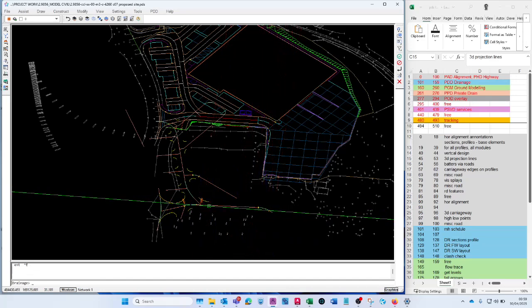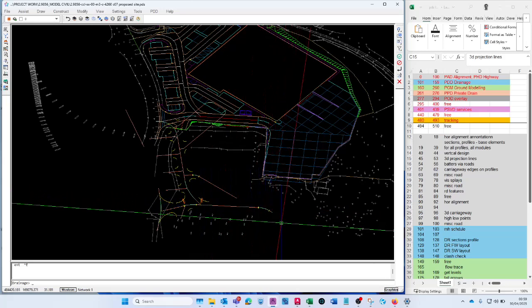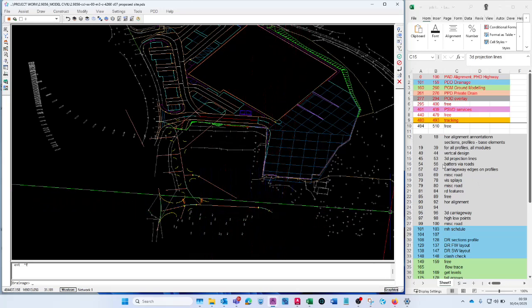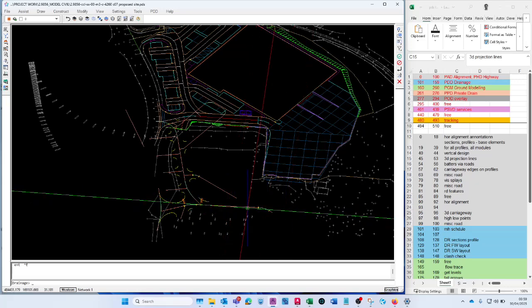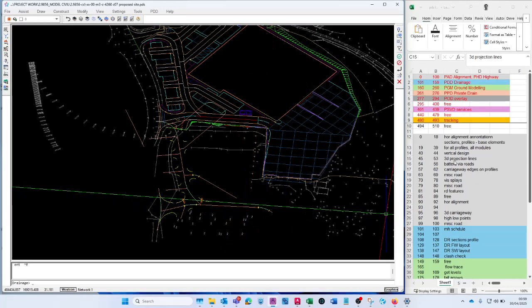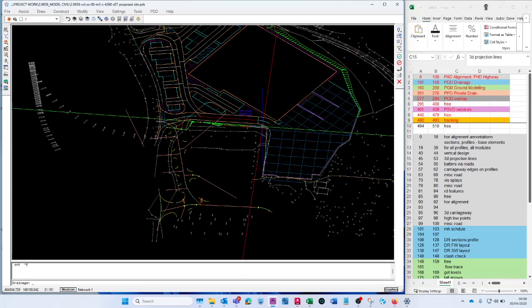So the truck is going to go straight along this road. It's going to turn and follow this little stub road. And so this is the 2D information that you set for the alignment, and this group is going to project this up, making it into a 3D surface based on the vertical design in that profiles that we just saw.